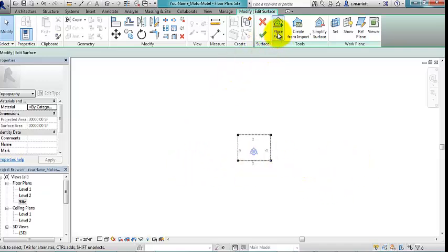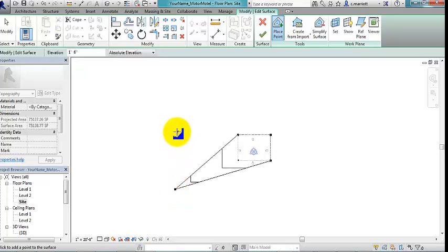All right, so I go back to place point. So I will make the high point of this gentle slope 1'6", and I'm going to come out some distance here so I can articulate my road later. I'm going to click here, and I'm going to click here. So it's a high point here, and it's sloping gently to my site.